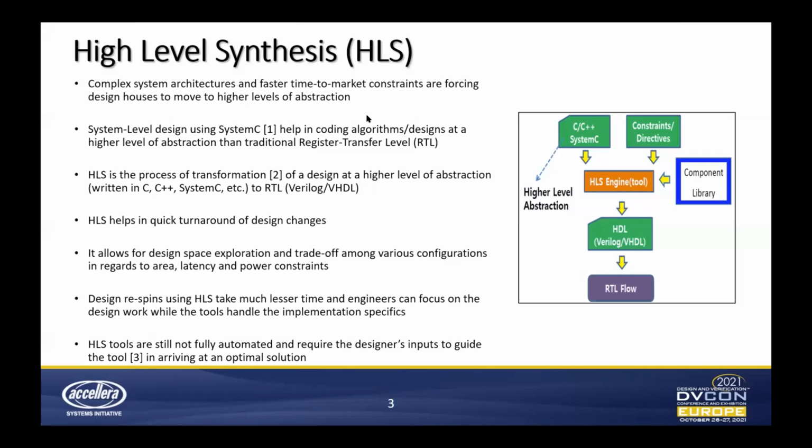HLS helps in quick turnaround of design changes and allows for design space exploration and trade-off among various configurations in regard to the area, latency, and power constraints given. Design respins using HLS take much less time, and engineers can focus on the design work while the EDA tools handle the implementation specifics.